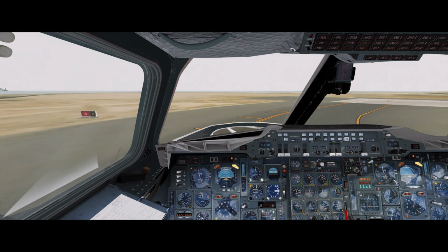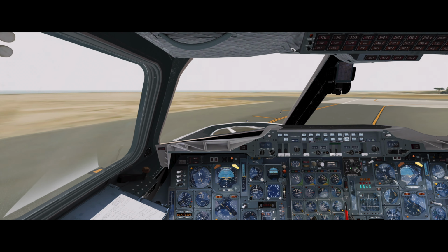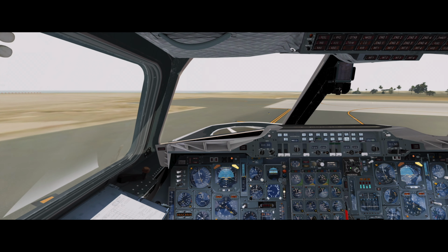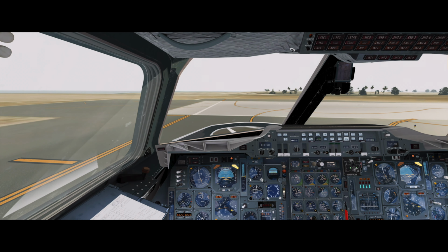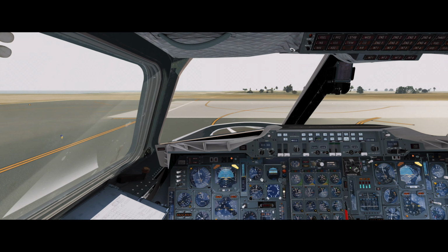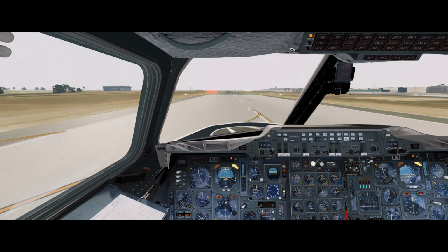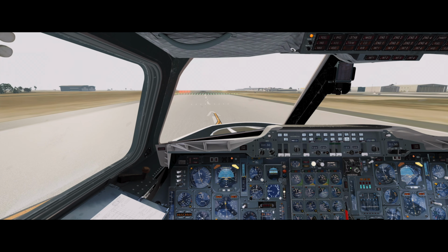Transponder. Squawking 2000. Wheel lights. Off. Yep, they're off here. Master warning. Called. There's nothing there. Inhibited. Takeoff monitor. Armed. Reheats. Selected. 4 white. Pitch index. 13 degrees. Radar. It's off. That's the before takeoff checklist complete.